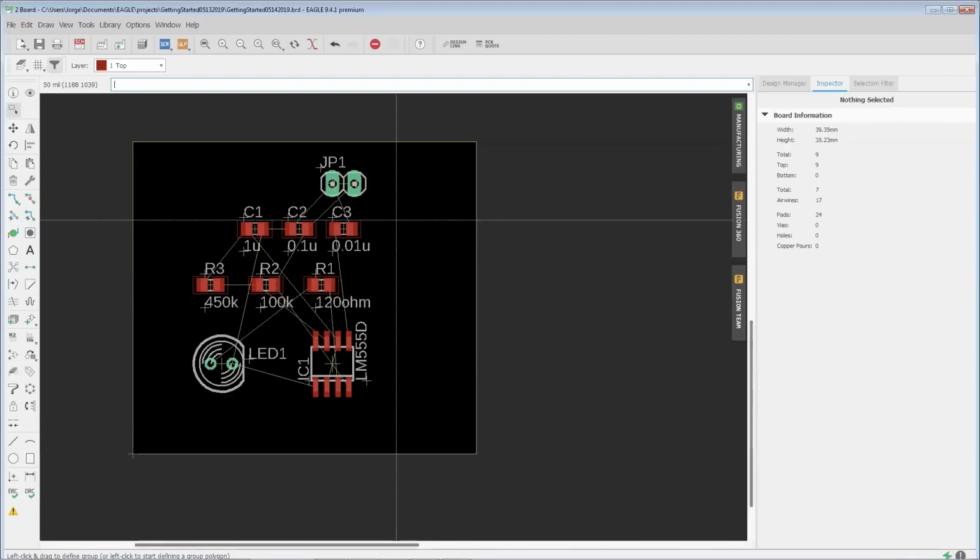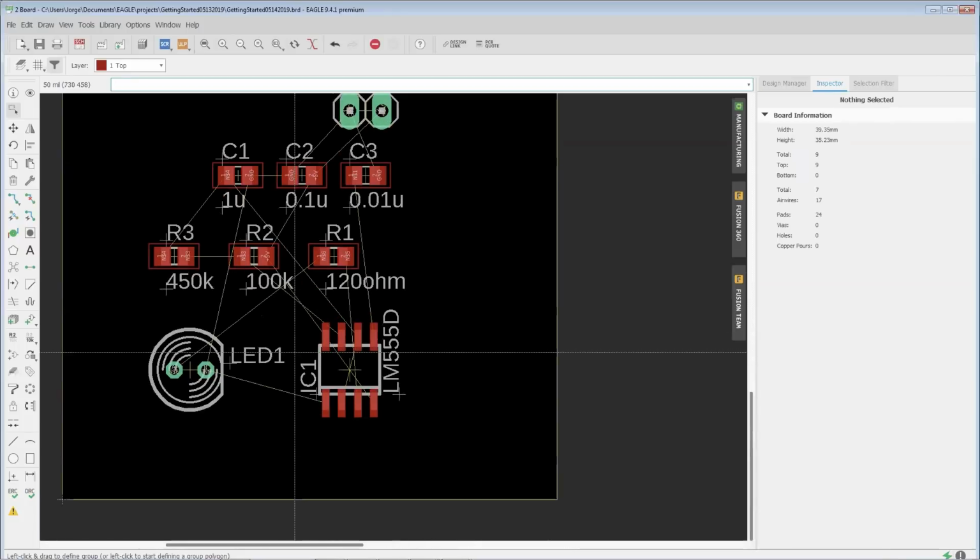If you're going to do high speed or RF, those things require a lot more care when doing the layout, because then the laws of physics really come to bear. If you don't take them into account, you can end up with a non-functional board just because the trace wasn't the right length or didn't match the right impedance. So even though we know we could just let it rip with the Autorouter, let's try to arrange things, get them a little bit cleaner and more organized.